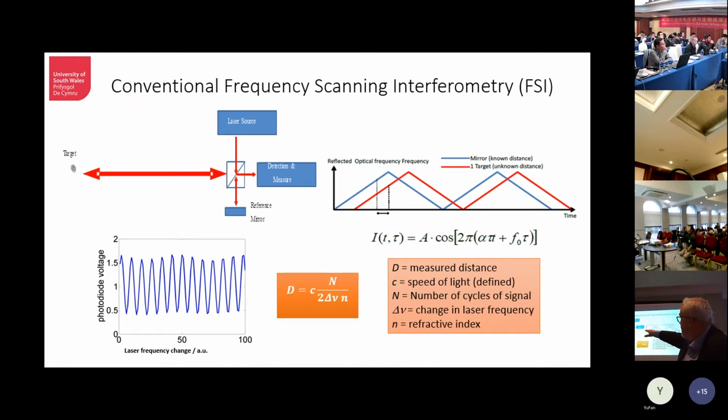And you can see we've got a laser source and the beam splitter. There's your Michelson interferometer. You create one mirror as a reference arm, and you shine the light up into space. At each point where you want to measure, you have a target. It's just a small ball lens. And if you look at the mathematics, if you make the ball lens have a refractive index of 2, it becomes a perfect retroreflector to reflect light back from that position. So a small lens, index of 2, gives you really good target positions.